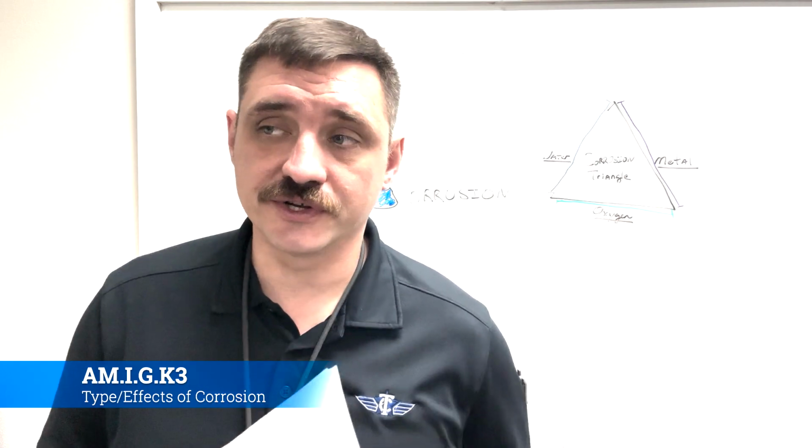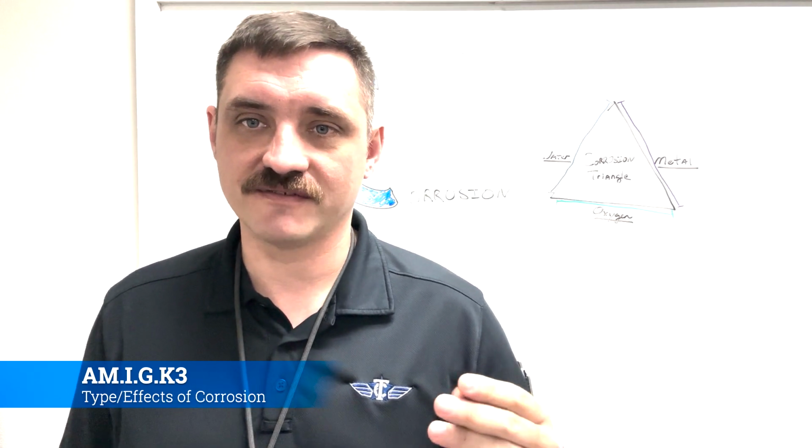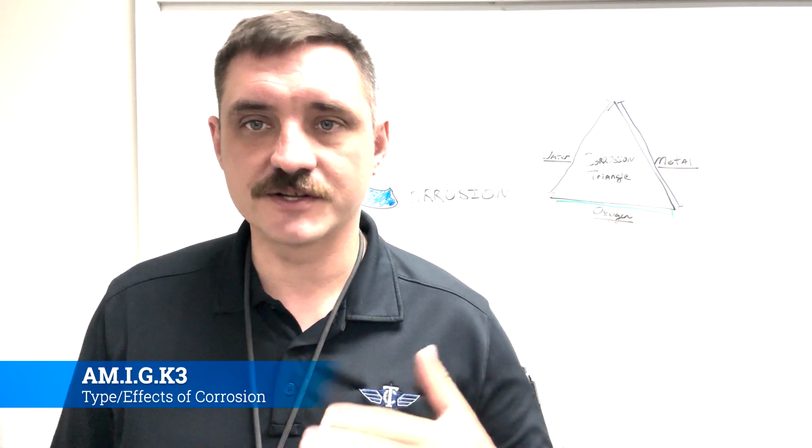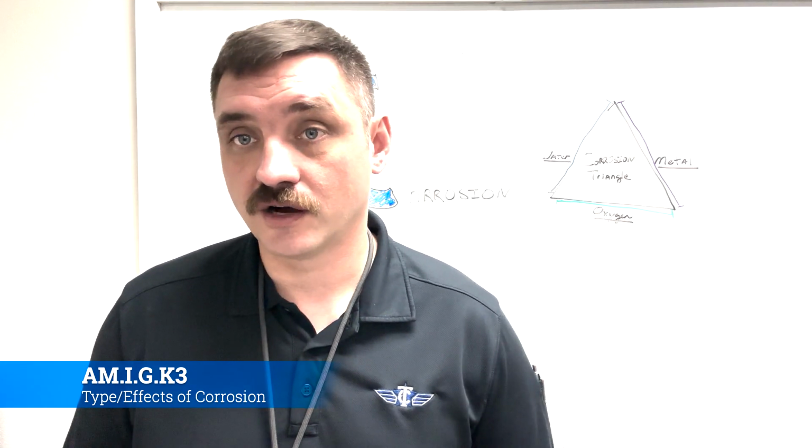With fretting corrosion, you'll end up having rivets that are like smoking rivets. You'll see all this black chalky stuff coming off of it. That's where you most commonly get fretting corrosion. It can be in other areas as well. Anything that meets that criteria will cause fretting corrosion given enough time.